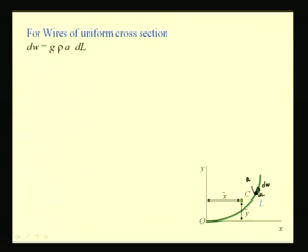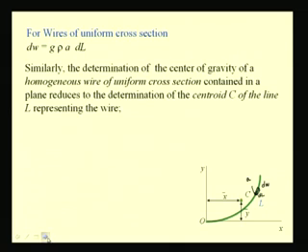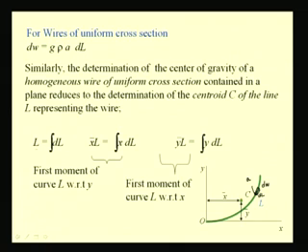So, we have dW as g times rho A dl, and if we integrate this, we can take out these constants like g, rho and A from the integration, because we assume homogeneous material and small objects. So, g is also constant, and we are additionally assuming a wire of uniform cross section. So, this A is constant.